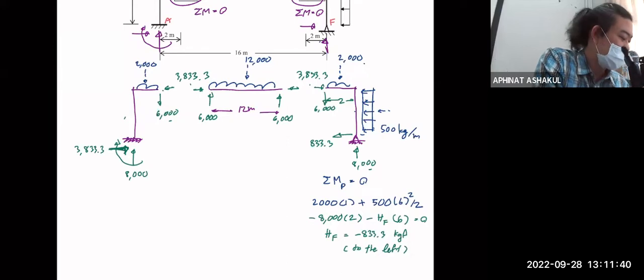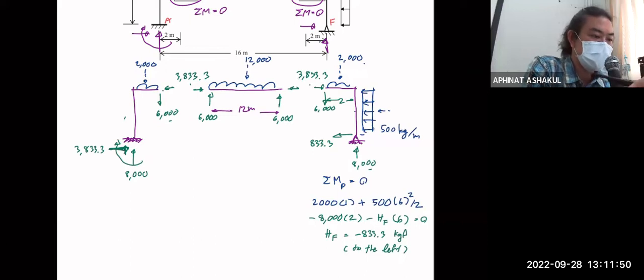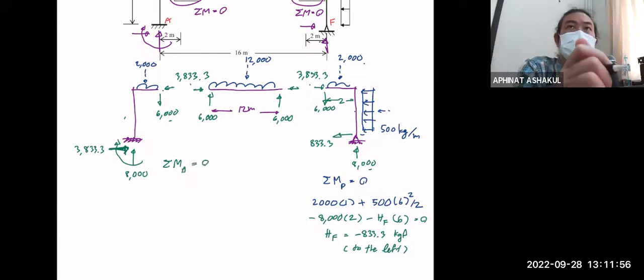Okay, and the moment you're going to have to calculate. So to solve this moment, you may want to take sigma MA equal to 0 to solve for this fixed end moment, right?